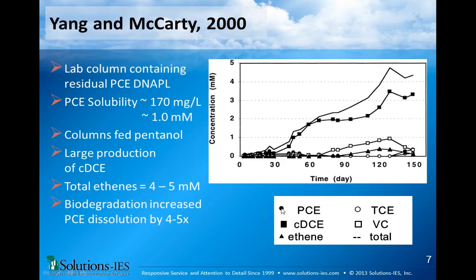Conceptually, it doesn't look all that different from a pump and treat system. I think the difference is that anaerobic bioremediation systems, at least the recirculation systems, generally have significantly higher O&M than pump and treat. First of all, you have to pay for the substrate. There's more monitoring and process control, and then there are more logistical problems with plugging of piping, biofouling, and stuff like that.